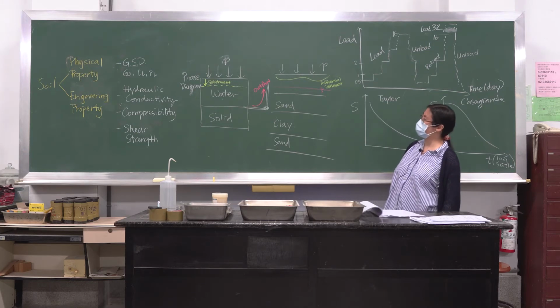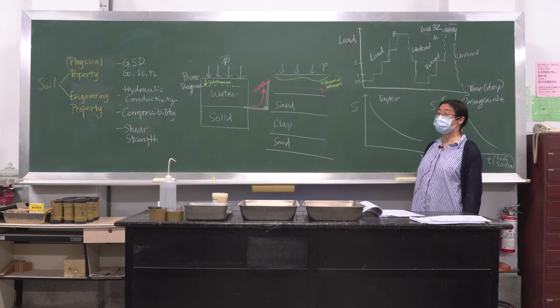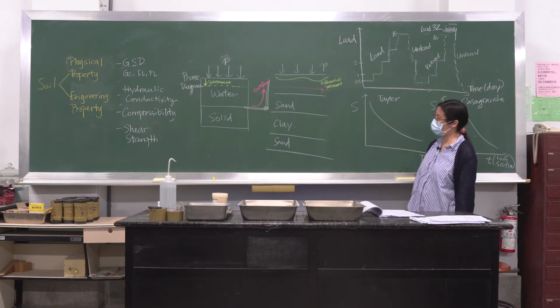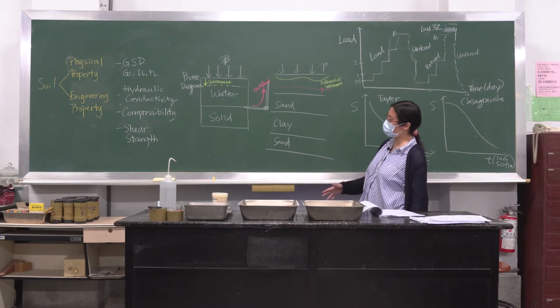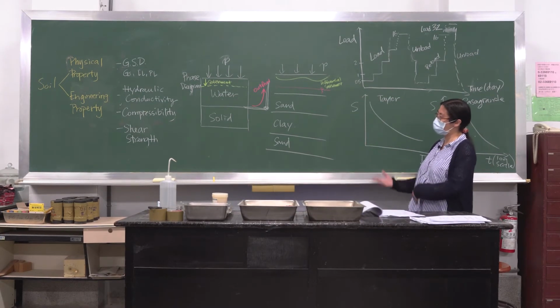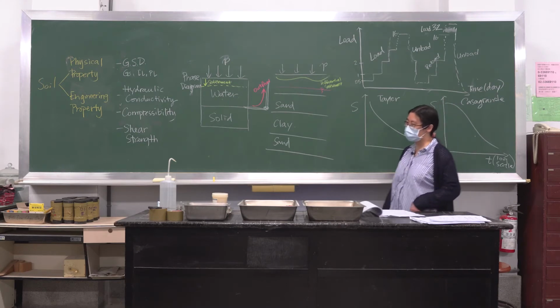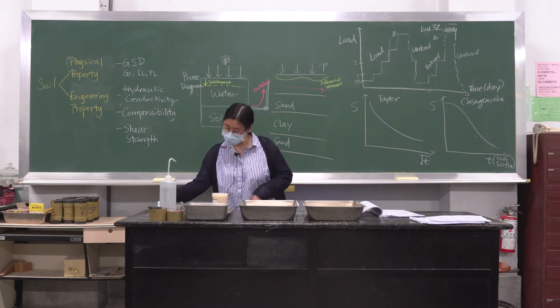What they have done is put a lifting jack under each column. When there is settlement, the jack lifts the structure up. In that way, the problem of differential settlement does not affect the performance of the airport. So those are two examples that we see in Taiwan and in other countries related to settlement. Today what we are going to do is perform a consolidation test.